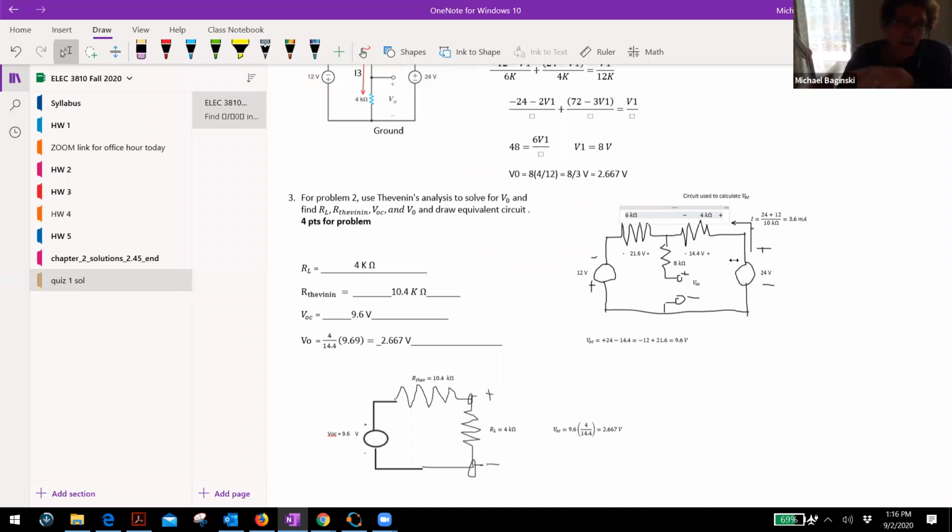14.4 volts. And that means if I start here at the negative terminal, I get an increase of 24, shown right here, and then a decrease of 14.4, which is 9.6. If I go this way, remember, I'd get a decrease of 12, and then an increase. Now I'd have plus to minus. It would be plus on this side, because current's flowing that way.